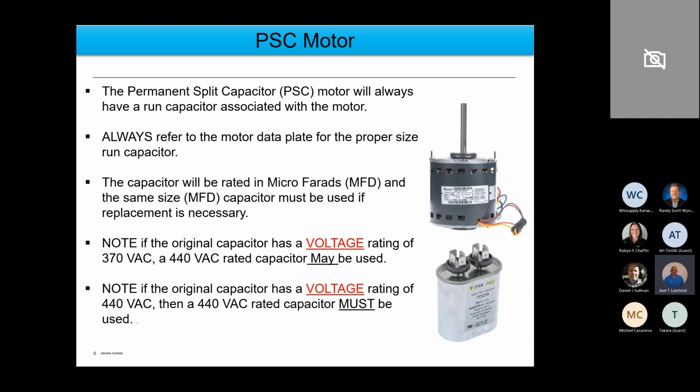It's a little heavy duty capacitor. You could literally have, as an example, though it would be pretty rare in our industry, a 10 microfarad capacitor with a 1,000 volt rating. So the idea is the voltage rating has to do with the ability of that capacitor to tolerate a particular voltage up to its rating.